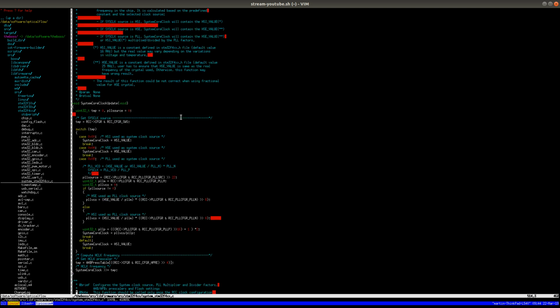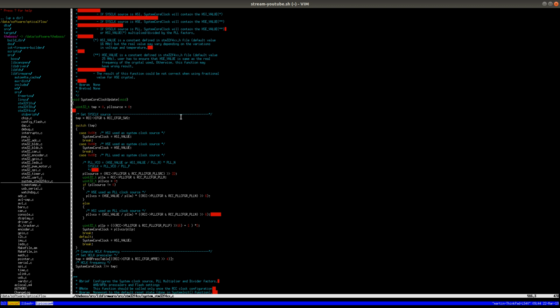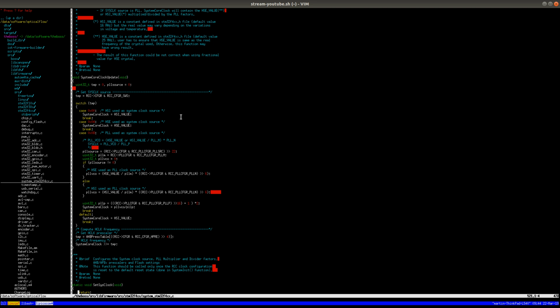And this fact is important because I'm running on top of FreeRTOS, and it's important for me that all the drivers are started from the init thread. So I can't initialize the drivers before that, because some of the drivers actually start services, and I want those services to start running before the call to the start scheduler, which actually starts all the threads. So if I don't run the drivers from a thread, then FreeRTOS is not actually running. So the threads won't start in time, and that's a problem.